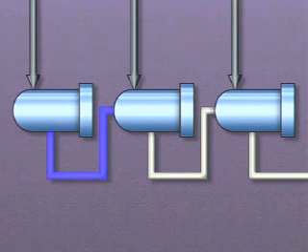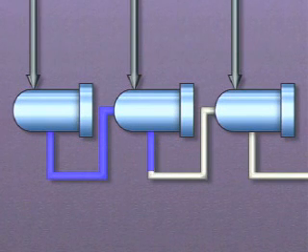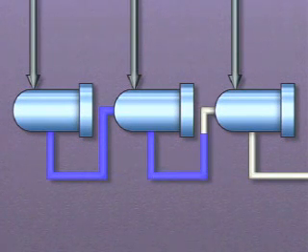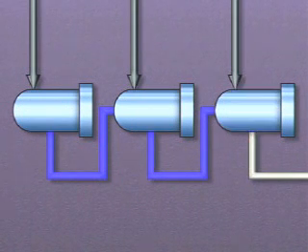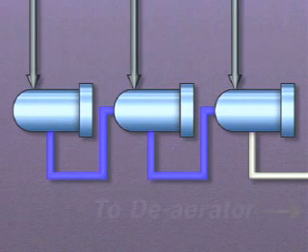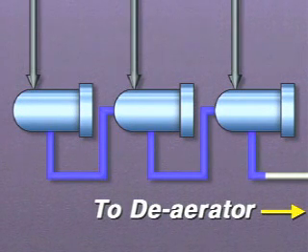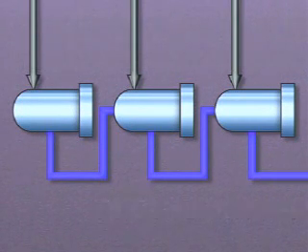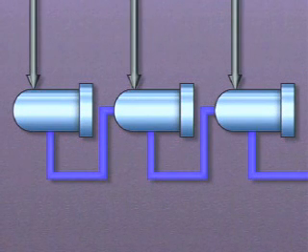In our example, the flashing and condensing process for the drips continues through the train of heaters until the drips from the heater that has the lowest shell temperature and pressure flow into the deaerator and become part of the feedwater. In other cases, such as in the operation of low-pressure heaters, the drips from the heater with the lowest pressure and temperature flow into the main condenser.